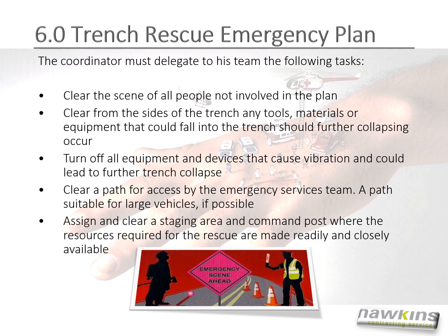During a trench rescue emergency plan, the coordinator must delegate to his team the following tasks. Clear the scene of all people not involved in the plan. Clear from the sides of the trench any tools, materials, or equipment that could fall into the trench should further collapsing occur. Turn off all equipment and devices that cause vibration and could lead to further trench collapse.